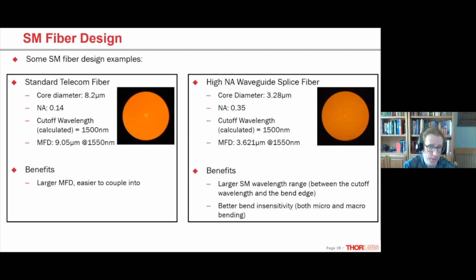There are also fibers out there, again keeping in mind that the index modifiers that create the core versus the cladding can be mobile. If you splice, let's say, this fiber to this fiber, there are certain fibers engineered so that in the smaller core fiber, the dopants, as it gets heated for that fusion splice, will move some and again create a natural taper on that splice, so you get good coupling efficiency. So there's definitely a lot of ways to do it, and that is engineered into certain fibers.